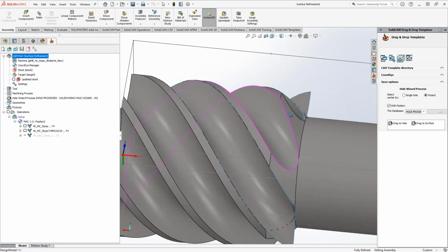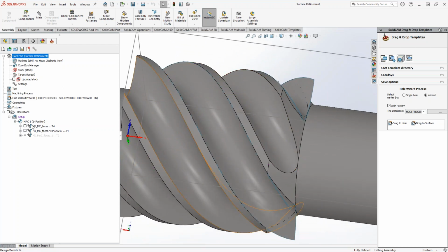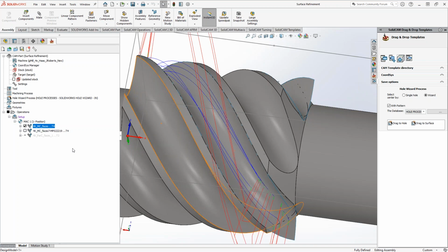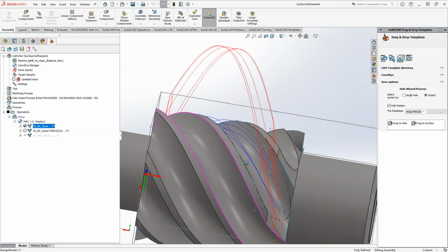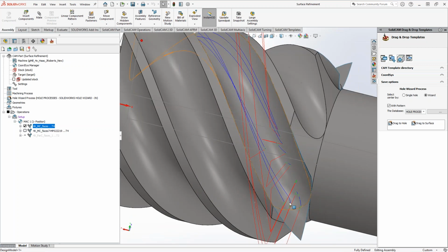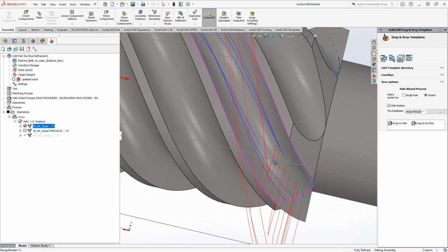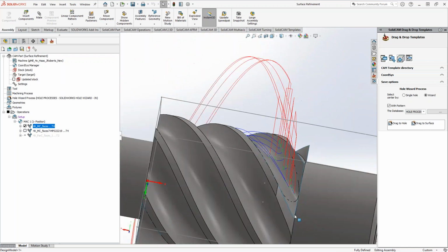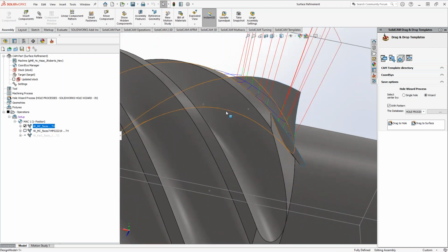If you take a look at any of these surfaces, they're pretty clean-looking surfaces, but when you try and use them for, let's say, this 4th-axis toolpath, you get this kind of disjointed toolpath here where it kind of stops short of certain areas. It's not the cleanest-looking one. But if I were to use the surface that you can see here that has those square edges, now I have nice continuous lines for my blend between boundary curves.